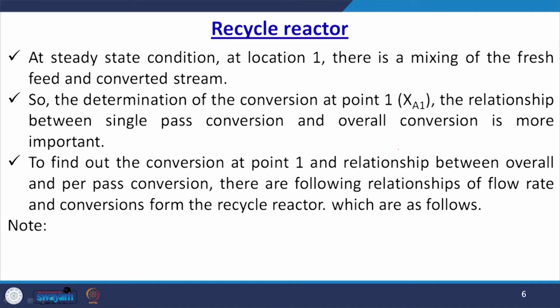Now, sometimes people may look into the steady state conversion in the concept of the recycle reactor. At steady state, at location 1, the inlet of the reactor, there is a mixing of fresh feed and converted stream. So, these two streams are being mixed. Therefore, the determination of the conversion at point 1 after time t, XA1, and the relationship between the single pass conversion and overall conversion is more important.